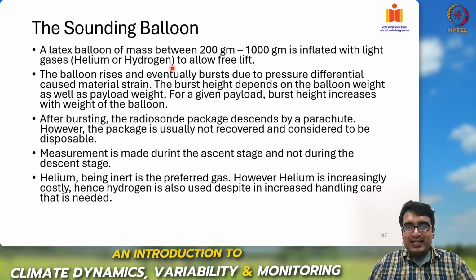The balloon rises and eventually bursts due to pressure differential caused material strain. So, as the pressure of the atmosphere falls with altitude, the balloon starts to expand outwards to maintain pressure equilibrium. This causes increasing strain in the latex material and eventually it bursts.